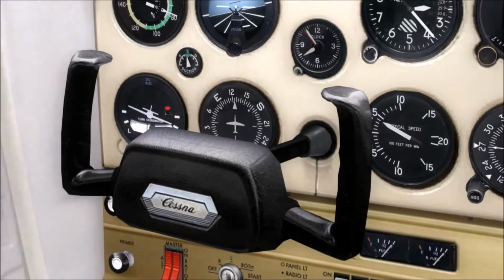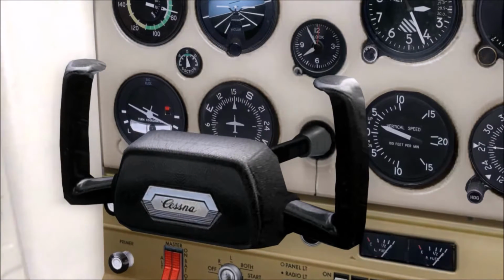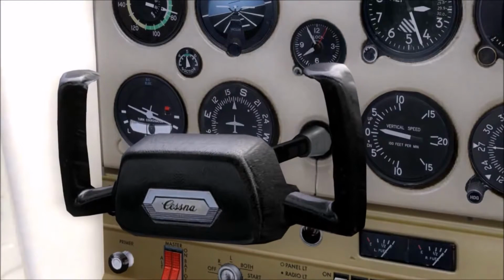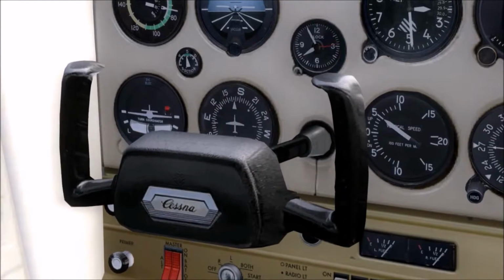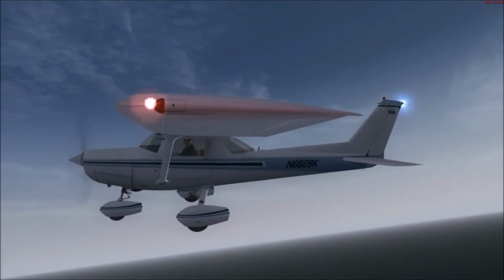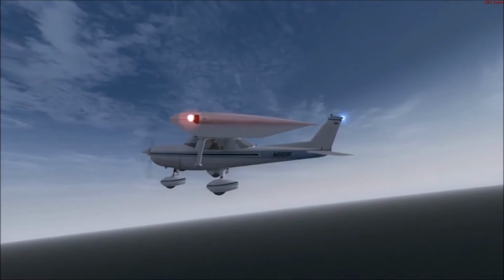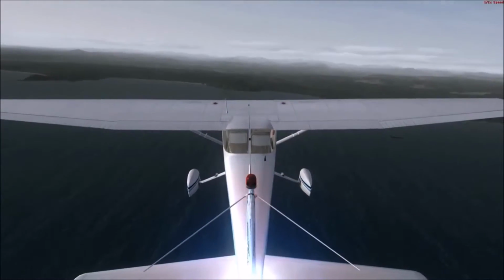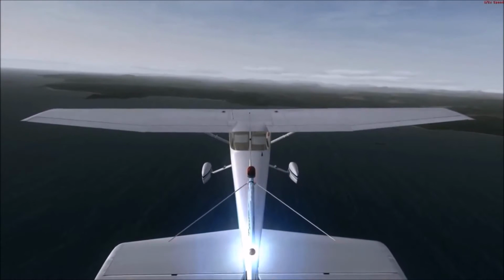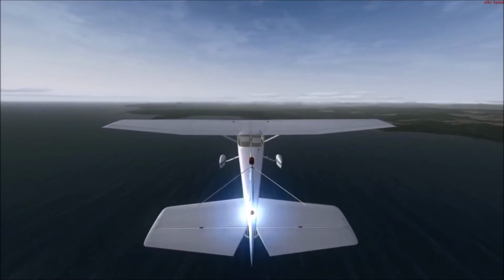While flying, I generally like to keep my aircraft flyable with my thumb and forefinger. This stable flight condition is only possible by use of a properly trimmed aircraft. In Flight Simulator, you aren't going to be able to feel the forces of the yoke pull the aircraft. You will, however, be able to see what the aircraft is doing in relation to the setting you want. It's much more difficult to trim in Flight Simulator than it is in real life.